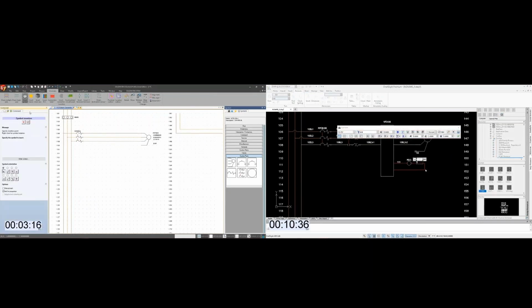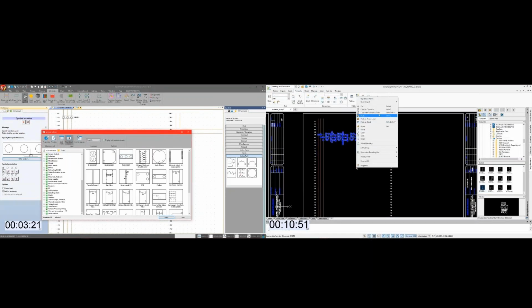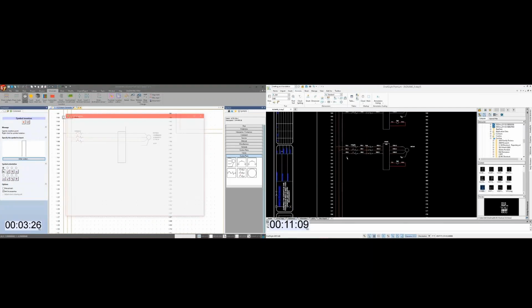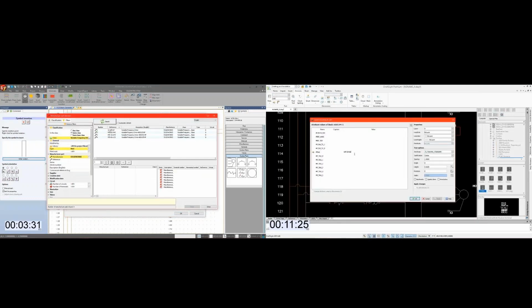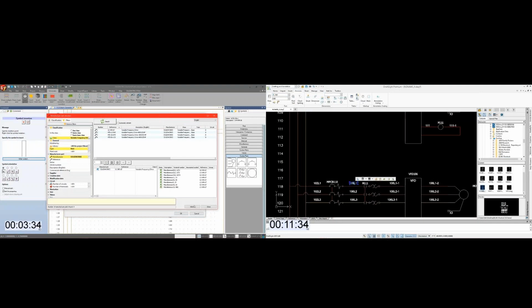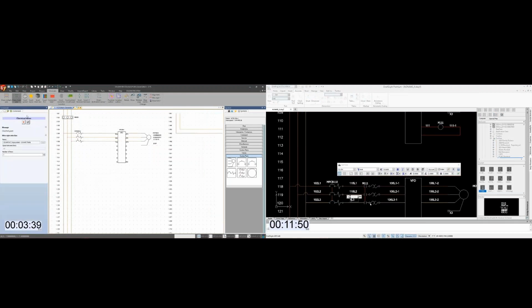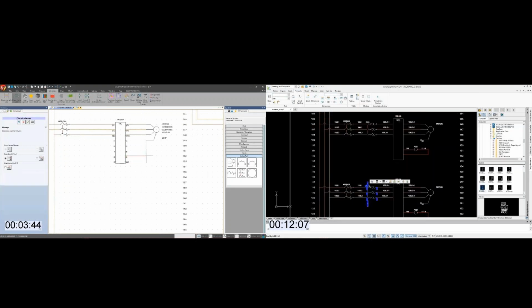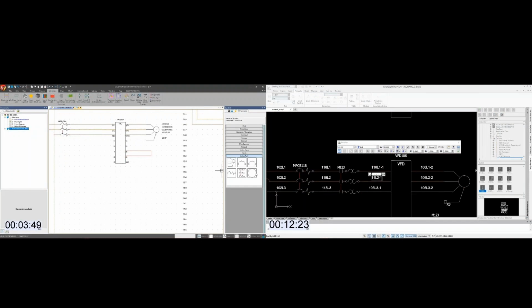Over here, back in SolidWorks Electrical, I'm 3 minutes in, continuing to place some intelligent components. So I got a circuit breaker put in. Here I'm going to go grab a VFD. So this is really nice. You know that VFDs have a lot of terminal connection points that have to be defined on those. This is a generic VFD symbol. So as I select the manufacturer's part, based off of the terminals associated with that, those appropriate terminals are reflected in that intelligent symbol. So just coming in here to continue working on this circuit, again, I have snaps that allow me to align with my connection points, just as I would have snaps over there in DraftSite.